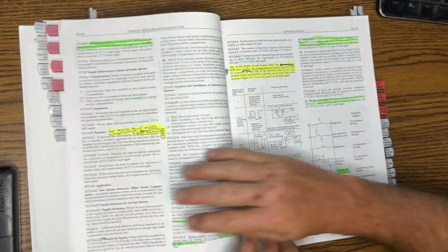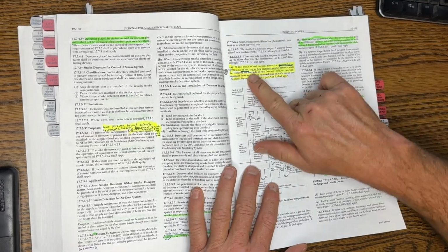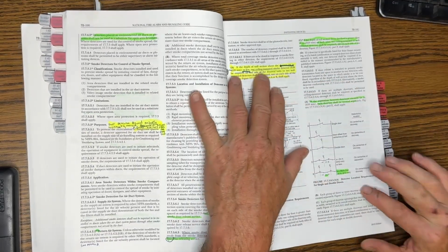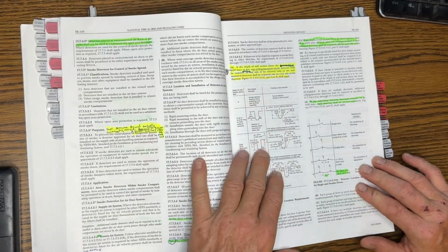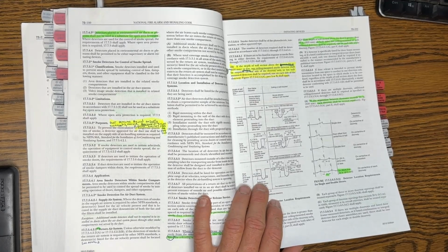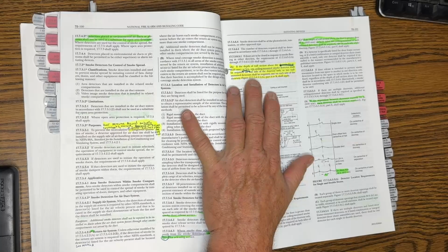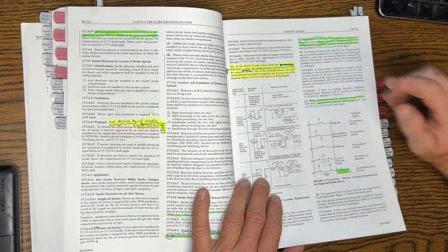Next one was 177561. 17. So right here, there it is. If the depth of the wall section above the door is 24 inches or less, one ceiling mounted, and so on. Just read that. I'm not going to read all these questions from this test, but the question that I wrote down in this online quiz is, a 17-inch deep wall section is above a door where the door separates 2 rooms. Where shall a smoke detector be placed? And based upon this, one ceiling mounted smoke detector shall be required on one side of the doorway only. That's based on that allowance.